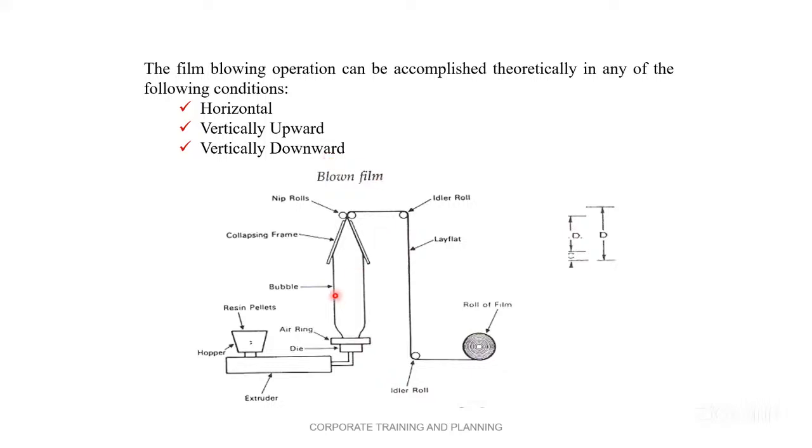Okay. Now see, this is the plant here. See, the die is here, the hopper is here. The same thing, nothing changed. But here the screw may be changed as per the design required for the blown film. Right. See the bubble here. It is very tall. Here you have to pass, compress here, in the downward direction, by which the bubble gets inflated.